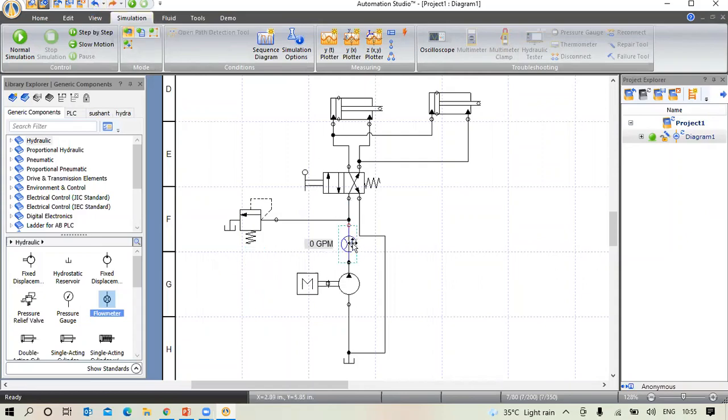Now press the shift key and move this component from here like this. If you take this component and place it onto this schematic, and after that if you want to place it onto the line, select the shift key. Now take this component, select and drag and drop it onto this line. Now you can observe the connection is proper, because at this point it indicates by black color, which means the connection is proper.